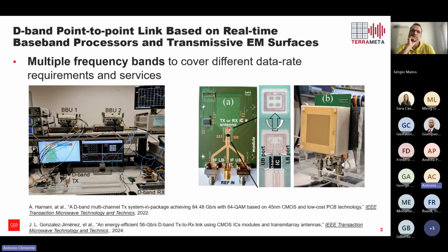A last problem is also that the phased array controls the phase, so you need to implement phase shift devices on the IC. The phase shift device can have a very high loss, and to compensate this loss, you need to integrate an additional power amplifier layer only to mitigate these losses. So you will have a structure that is very lossy, and you need to add an active device to compensate the loss. You will have more power consumption. So for me, this is the reason why.